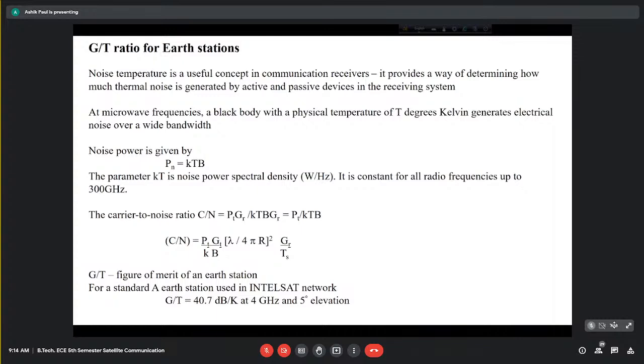Ideally, the initial stages of a superheterodyne receiver will have large bandwidth. And as you progress down the different blocks of the receiver, starting from the RF amplifier, then on to the mixer, local oscillator, then the IF amplifier, detector, and so on, the bandwidth is gradually tapered off so that the undesired signal components or out of band signals are gradually removed from the signal.